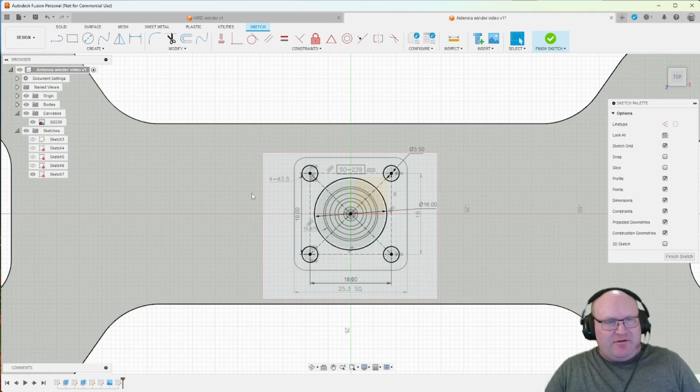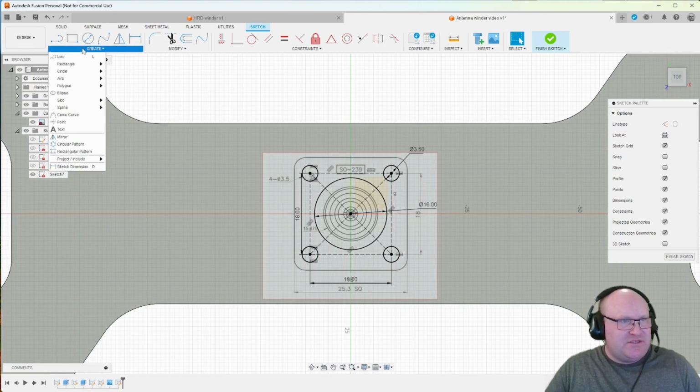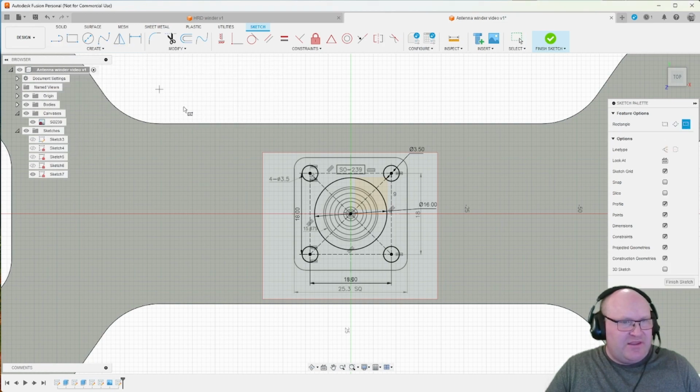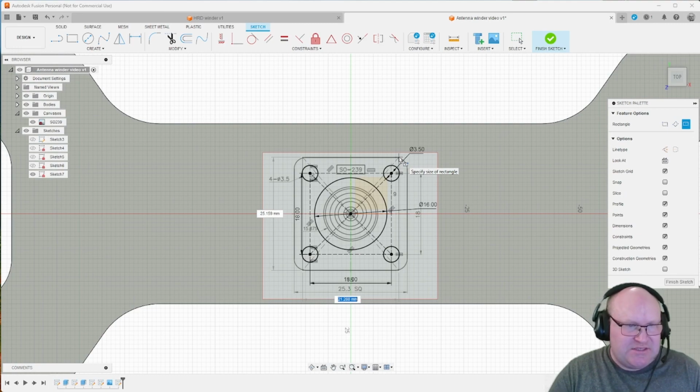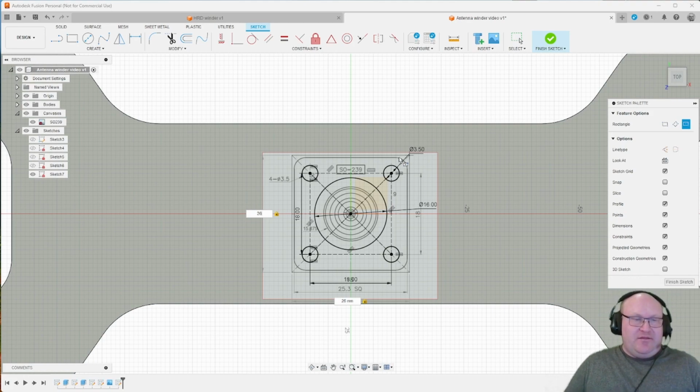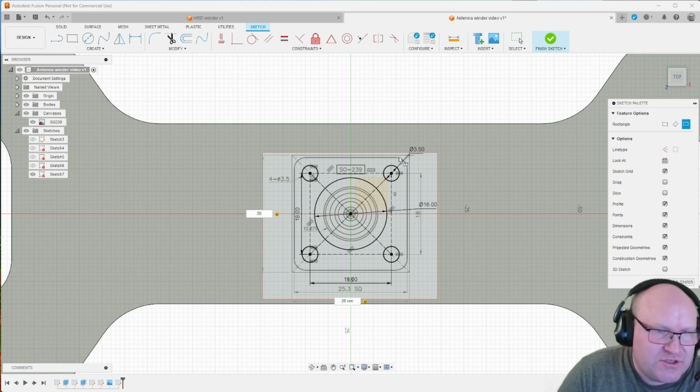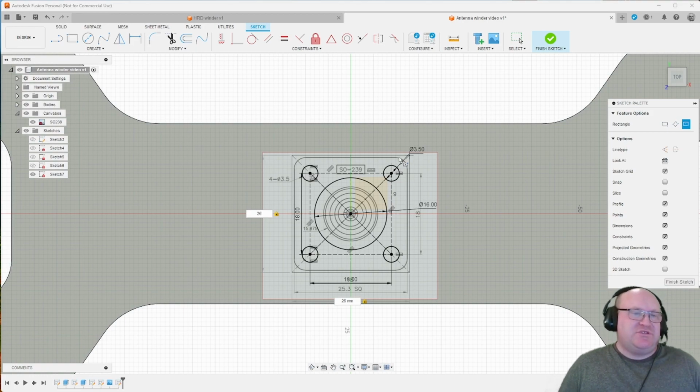The last thing we're going to add now is the outer hole, the one that the SO239 is going to fall into. So let's go in here, create another center rectangle there and there, and say that that is 26 by 26. That will give you some leeway on the 3D printer calibration so that you can actually get the part in. Of course, if you have a very nicely finely tuned 3D printer, you can go with exact dimensions, but it's always nice to have some wiggle room. Also, some of these parts are slightly off, at least if you buy the cheap ones off AliExpress.